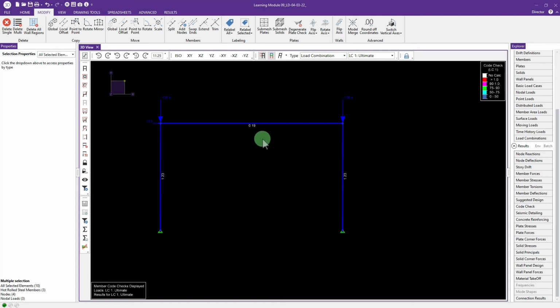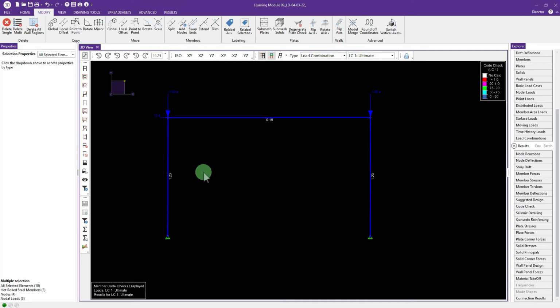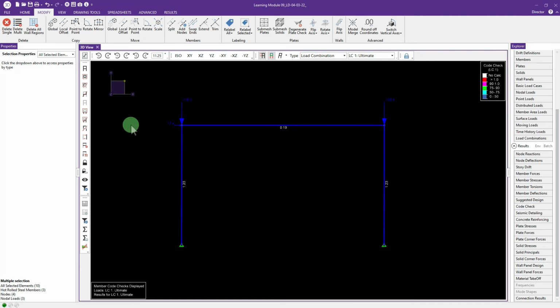So you must break your member into additional sections. This is something that is missed oftentimes by certain engineers. It gives you a more detailed analysis. So you must break it down into additional nodal sections to get more correct answers, if you will, or get the correct answer. All right, so let's go ahead and copy this thing over.